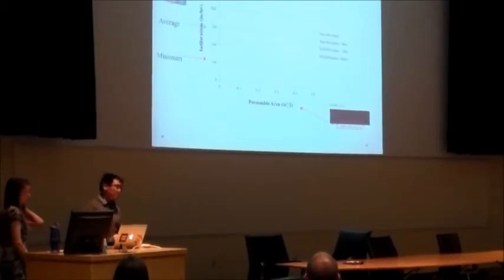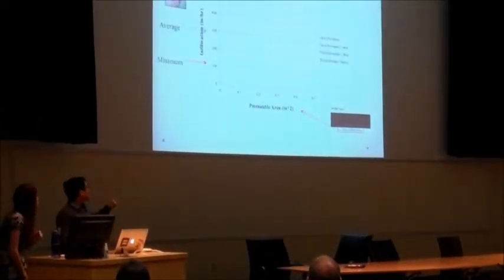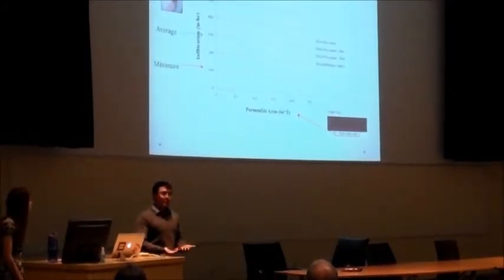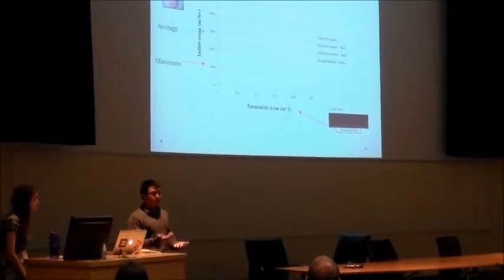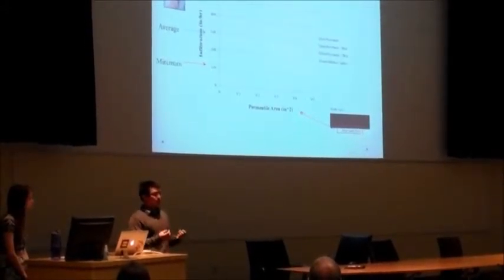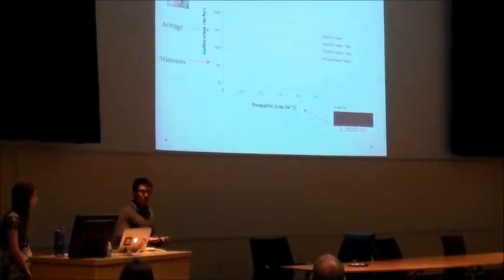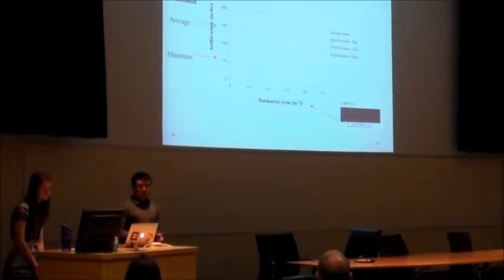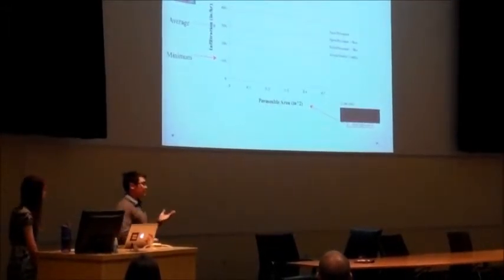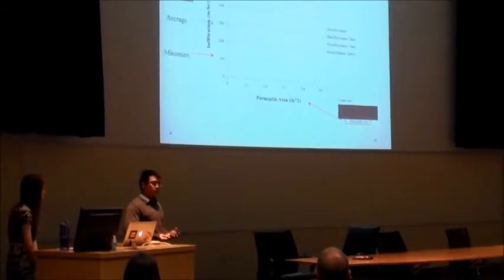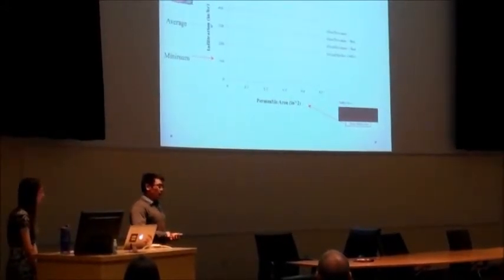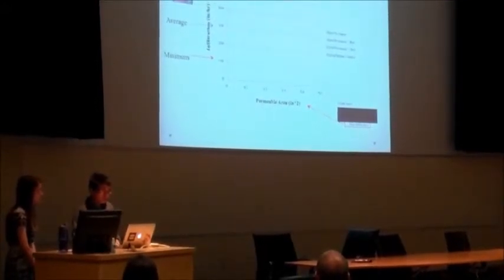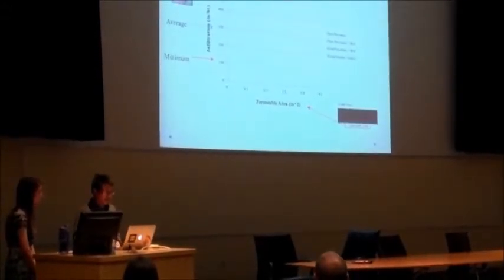So here's the infiltration rate on the y-axis and the permeable area also, which is the total permeable area of the bottom of the pavement. So that's the sum of total area of the holes which are permeable to water. Let's assume that the rest of the concrete is impermeable to water. And this is because the bottom area of the holes governs the flow. The outflow dictates the amount of inflow, assuming that there's no storage. And it's called the continuity equation in fluid mechanics.